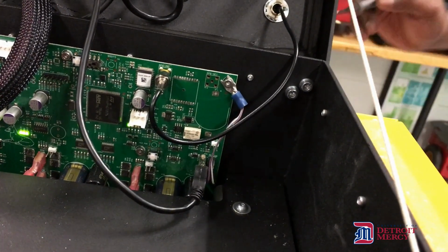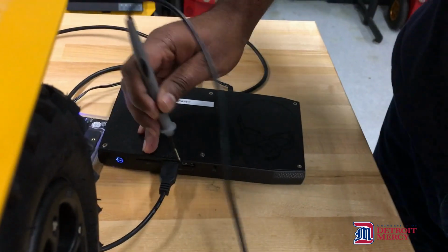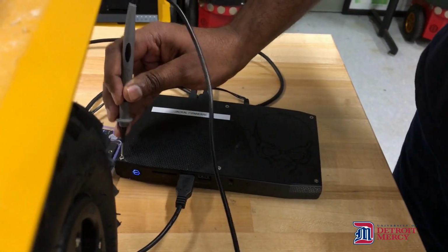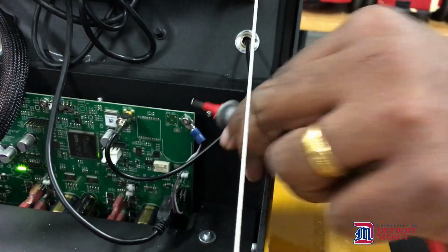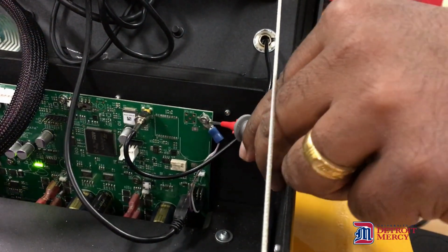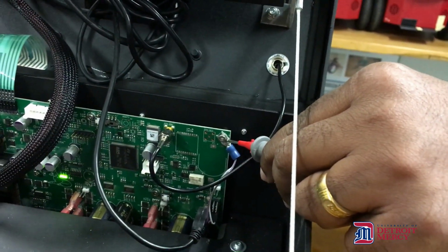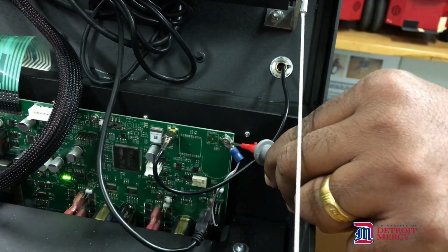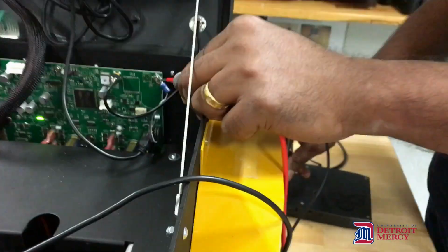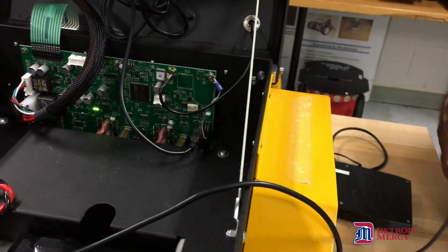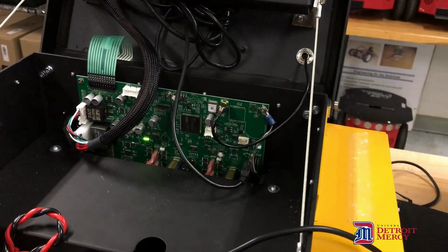Now we are going to check whether the ground is connected properly from the NUC. So if you come back here, I'm going to keep one end of my multimeter here on the NUC, and another end on the Jackal. You can see it's connected now. The ground of the NUC or your laptop is now connected with the ground of the Jackal. So now we can test whether our problem has been resolved or not.